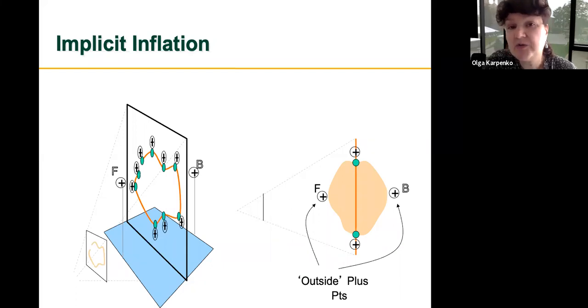Once we add those constraints, we can compute an implicit function that's supposed to pass through some of those constraints and be negative or positive at some other additional points that we created and that are shown by pluses. And then we can take its level set. Basically, we can just see where this function is 0. What are the points where it's equal to 0? Those points will correspond to our surface, the one that we want.